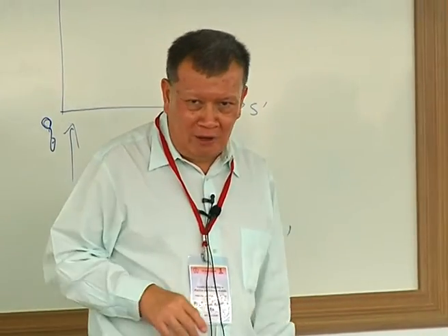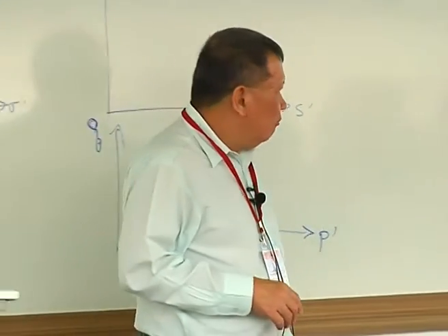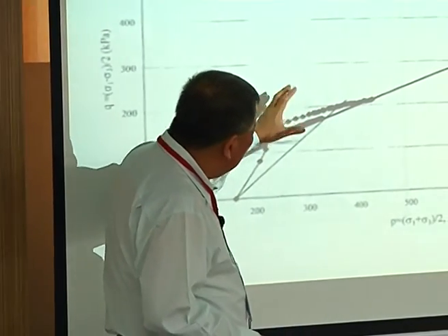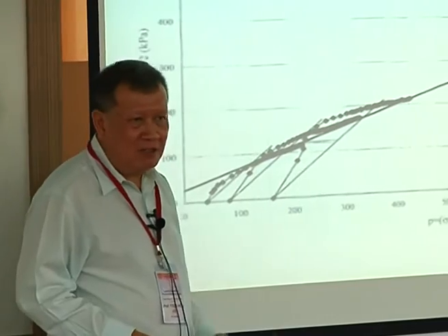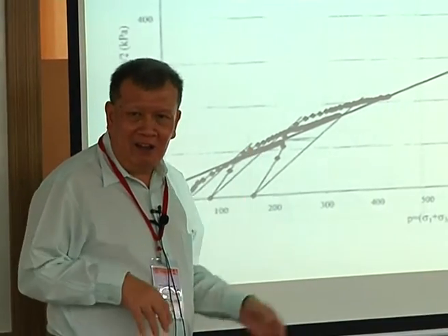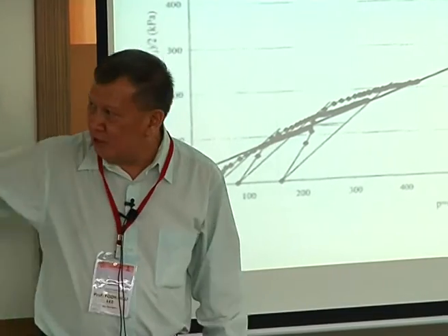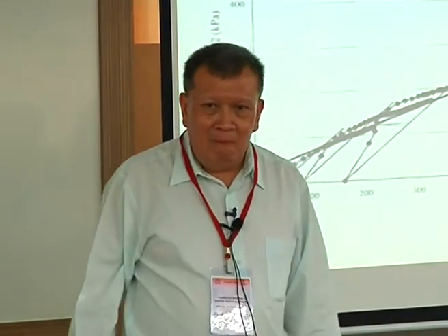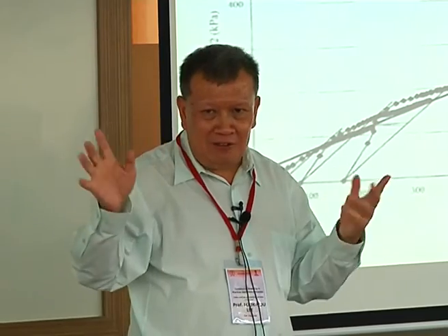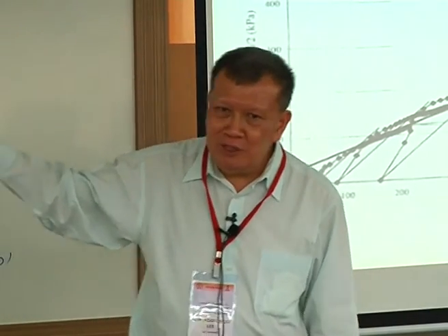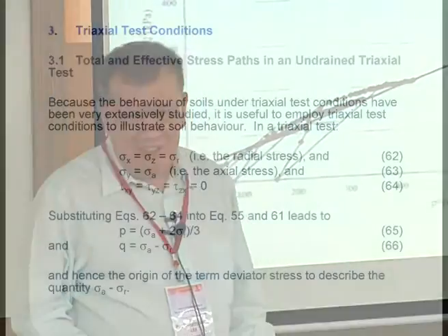Most real soil models will have this imperfection. If you ask me, this kind of magnitude of discrepancy, I'm okay with it. But I suspect the line was actually deduced from the Mohr circle, because the guy has to make sure that the 2 lines are consistent. I think he doesn't know how to do it the other way, so the engineer will only do this and then use it to deduce that.